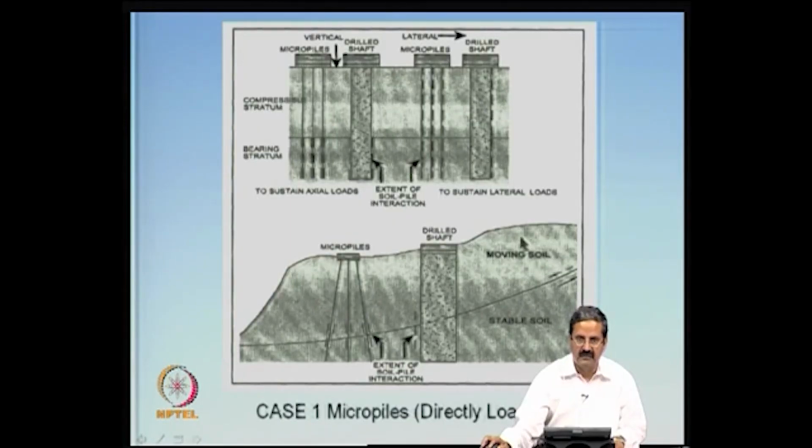So, the driving force divided by resisting force is the inverse of the factor of safety, or from the force equilibrium considerations you calculate the resistance divided by the driving force, which is nothing but the factor of safety. You have to calculate in terms of the moments, in terms of the horizontal forces, in terms of the vertical forces and all that. You have to meet all those equilibrium equations and calculate the factor of safety.